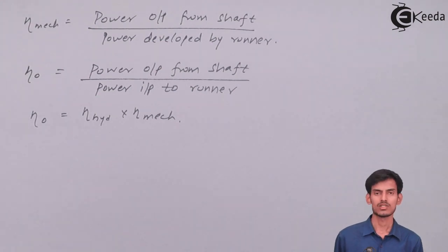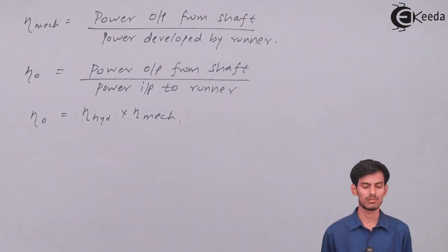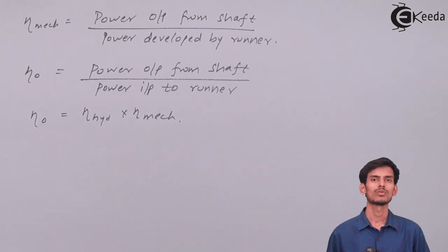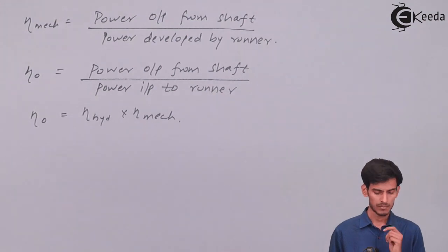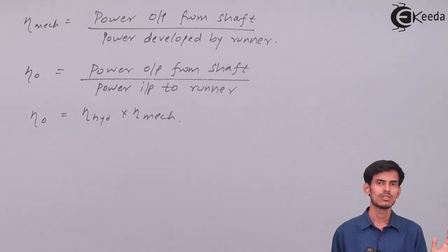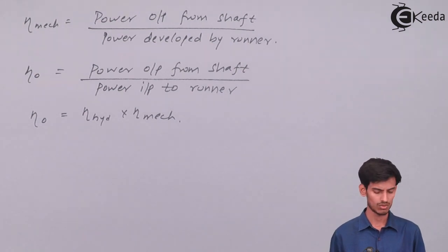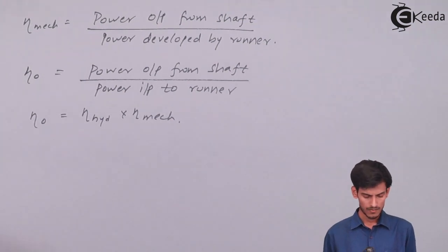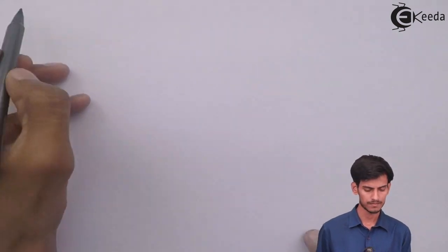Next is the discharge for this particular turbine, the Francis turbine. The value of discharge is the same formula. Q is A times velocity, but unlike the Pelton wheel where you had a cross section area, here you don't have a cross section. Here the flow enters through the sides, through the circumference. So the value of area changes. The discharge for Francis turbine has a bit different formula.